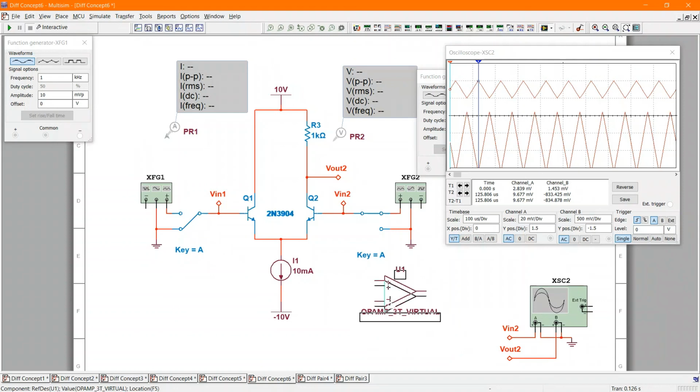We usually break that down into a simpler schematic symbol, which is a triangle where we have an input. We have two inputs, 1, 2. So here's one input, here's one input. So there's my two inputs. Those are these two inputs here. This is the positive input, so that's the non-inverting input. This is the negative input, so that's the inverting input, and this is the single output.